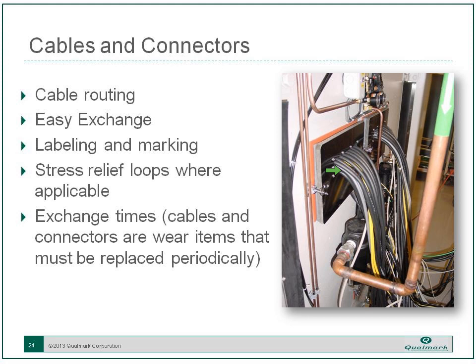But worry about exchange times with the cabling, making it so that it is not easy to get them mixed up. Make it as idiot-proof as you can when you have that many cables coming in and out. Keep everything labeled and marked. Put in those stress relief loops where applicable. You don't have a lot of excursion on the product when it's in HASS, a few centimeters at most, so you don't need to worry a whole lot about having lots of slack in the cable, but there's places where you need it, and you don't want to have cables coming unplugged or seeing undue stress.